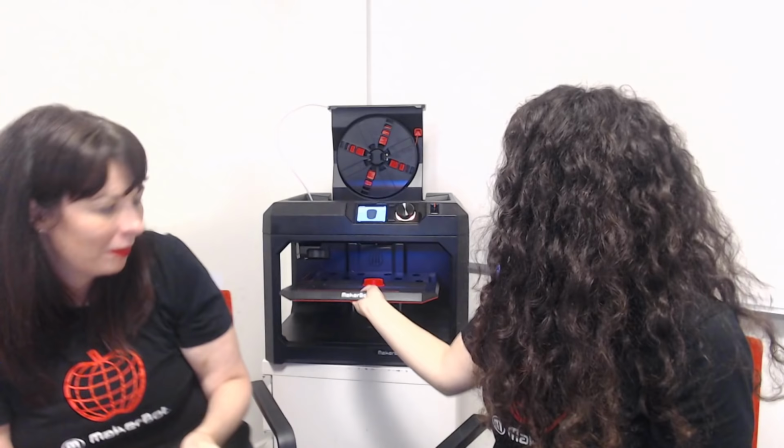Oh, absolutely. In the MakerBot Print software, you'll see that there's a virtual build plate. You can actually insert multiple models on that virtual build plate. So say you want to print 2 cylinders, these were actually 2 drumsticks. These 2 were printed together, and so you can have them like that on that virtual build plate, and then slice it through the MakerBot Print software.